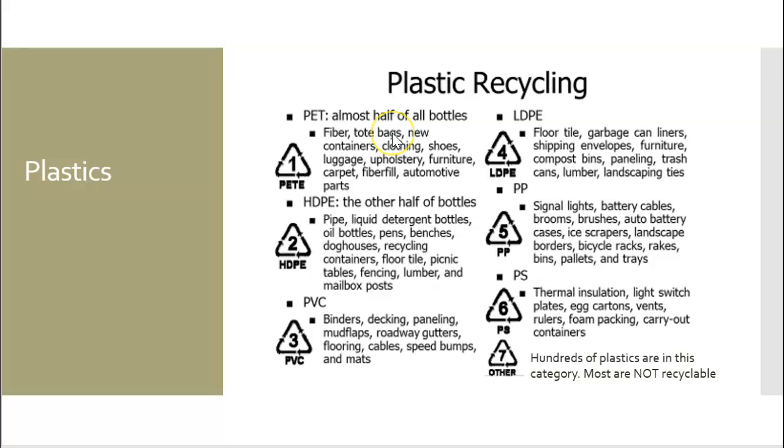The industry came up with these 7 numbers because they indicate the largest types or quantities of these particular plastics. So there's PET. A lot of soda bottles are made with PET. Then there's HDPE for things like milk containers, PVC, that's polyvinyl chloride, and then you have low density polyethylene, LDPE. That is used in a lot of plastic bags, one-time use plastic bags. Then there's polypropylene, which is made for a variety of different products. And then there's number 6, PS, which is polystyrene, something that you've seen quite a bit. So basically the foam containers.